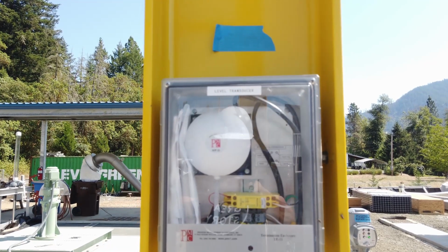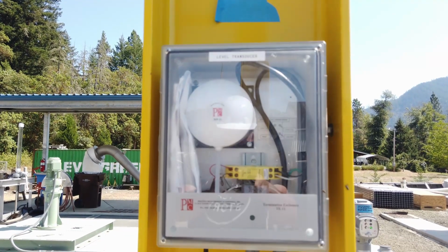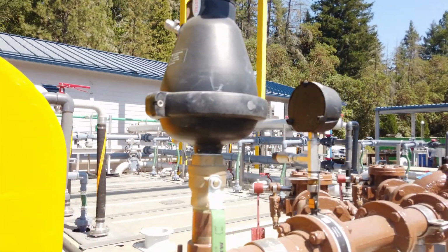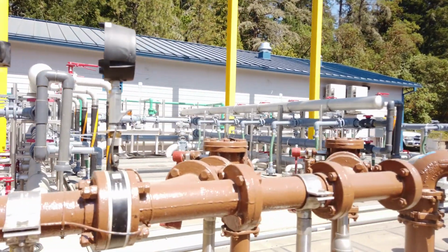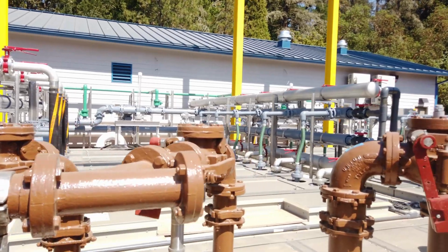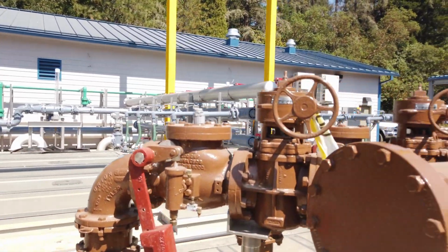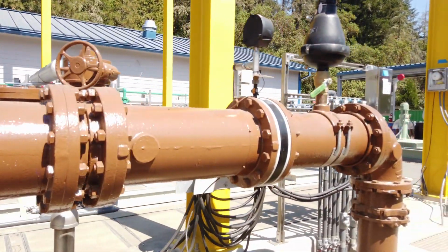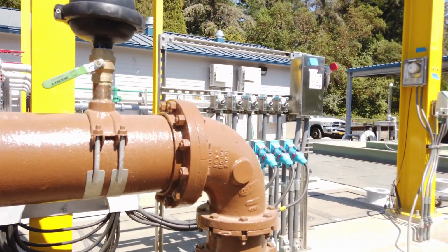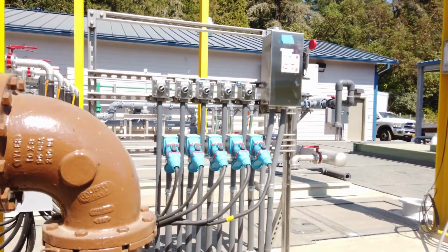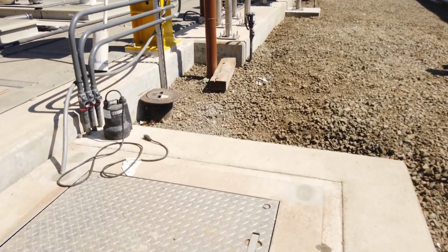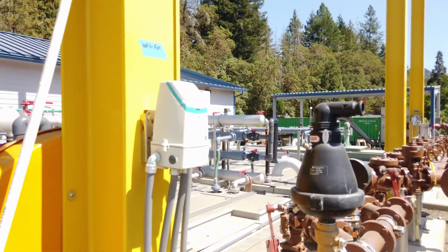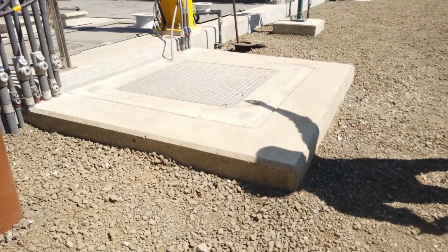A pressure transducer is installed to monitor the liquid level in the RAS-WAS tank. The speed and flow rate of the permeate pumps is increased as the liquid level increases. As the liquid level lowers, the speed and permeate flow rate drops. During the nighttime this time of year, because of low flows and low I&I, the system goes into nap mode a considerable amount. For process control purposes, we have magnetic flow meters on both the RAS pumps and the WAS pumps.